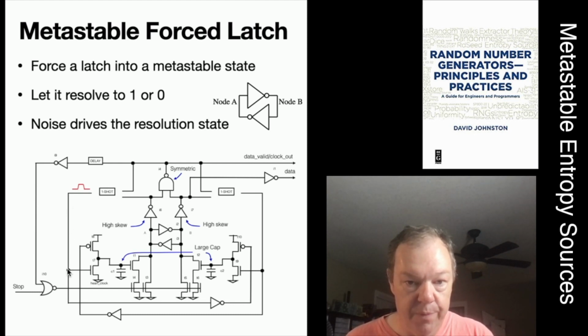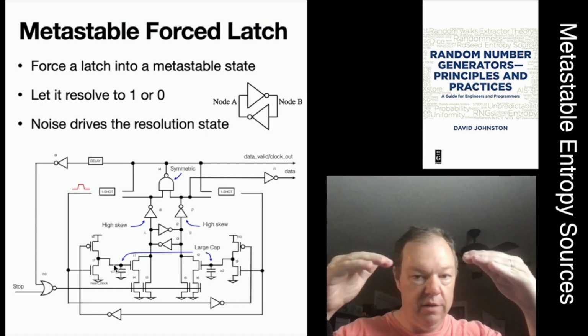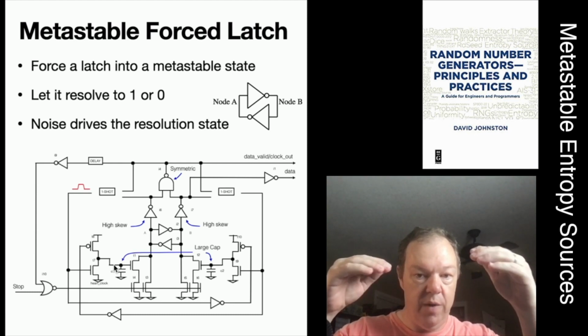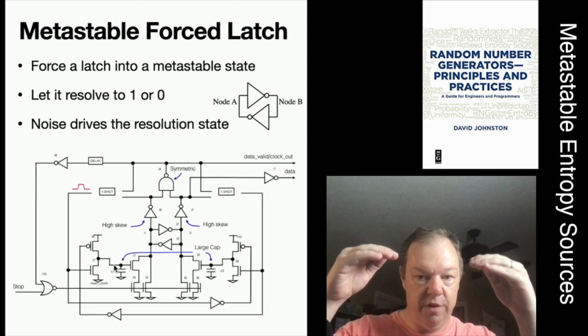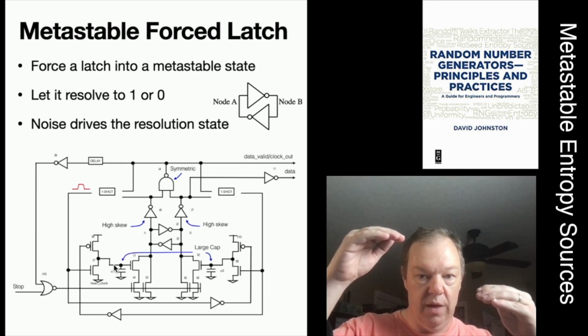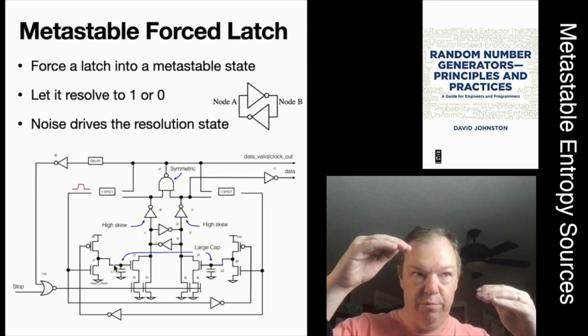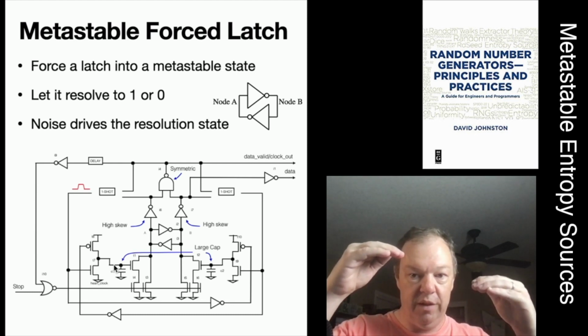It will come through here, and it will turn on this transistor, which will pull some charge off this capacitor. It will also carry on around here and turn on this transistor, which will push some charge onto this capacitor. If this one fires instead, it will pull some charge off this capacitor and put some charge on this capacitor. So the two capacitors are somewhere in the middle, but if you get a number of 1s out of the circuit, it'll push the capacitors apart from each other in a direction which will weaken the side which is producing the 1s, or the stronger side, and so it then moves back again.